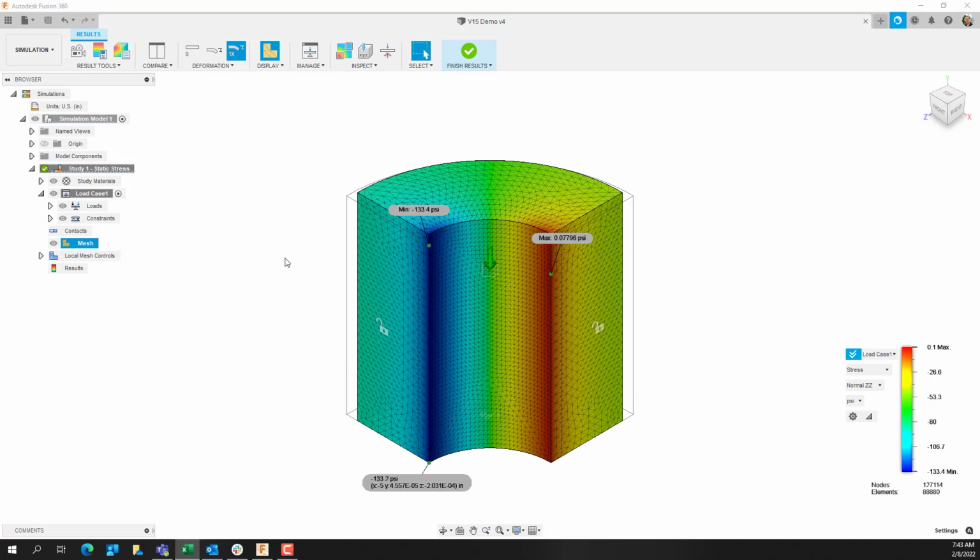So just to finish up, the last thing that I was saying about that is when you do work on a model, you do one mesh and that gives you a result, correct? And then you do 2 meshes and that's going to give you another result. But chances are, except in very few cases, those 2 different meshes are going to give you 2 different results, not necessarily the exact same result. And the question I get a lot of times is, well, which one is correct? It's a little bit hard to tell unless you have done a hand calculation and know exactly what that value should be. If you know what that value should be and that's what your simulation tells you the output is, then that's great, right? You've matched what the hand calculation should be.